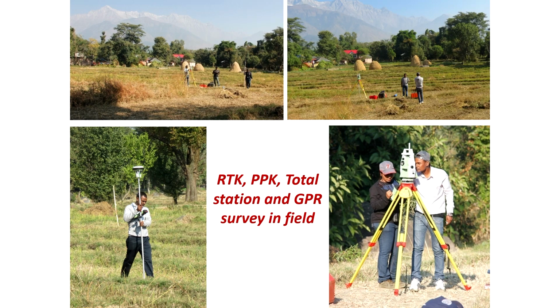So, we use the robotic total station. Now, many of us who are in this field, or maybe are using it for topographic mapping, mostly use the robotic station. Okay. Now, the robotic station has the advantage that it will lock onto your prism, and wherever you move it will automatically try to connect itself. So, a single person can do this mapping.